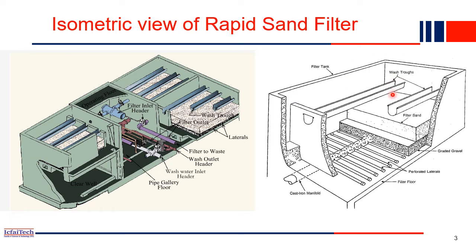So gradually water will simply percolate through the sand bed and then the gravel bed, and then water will be coming here, right? So here you have these pipes laid down. These pipes we call laterals. These laterals will have holes. Small holes will be there in this pipe.